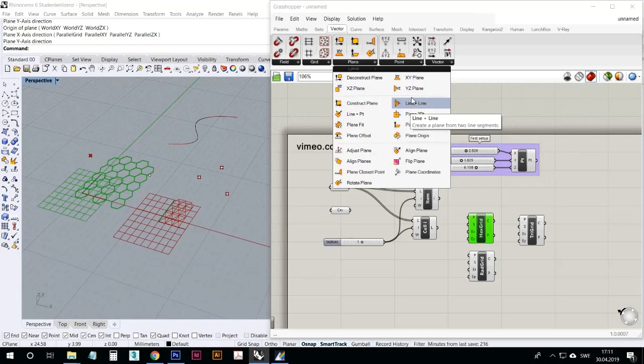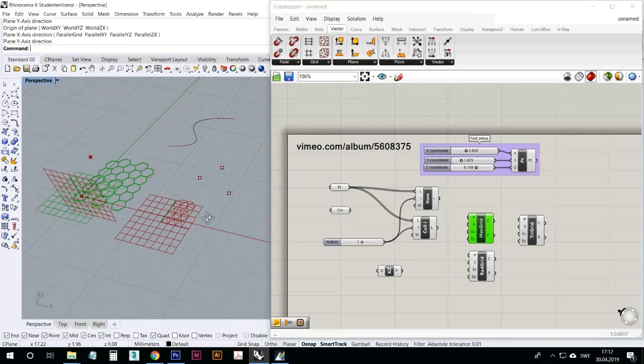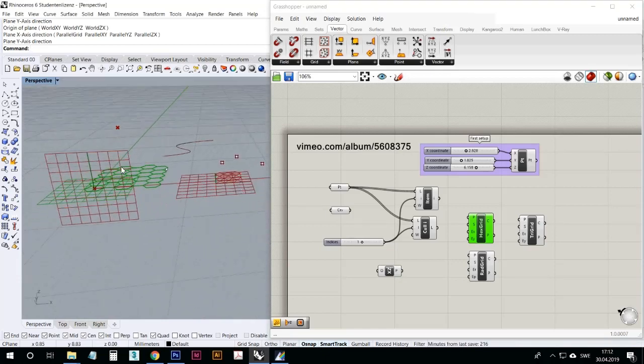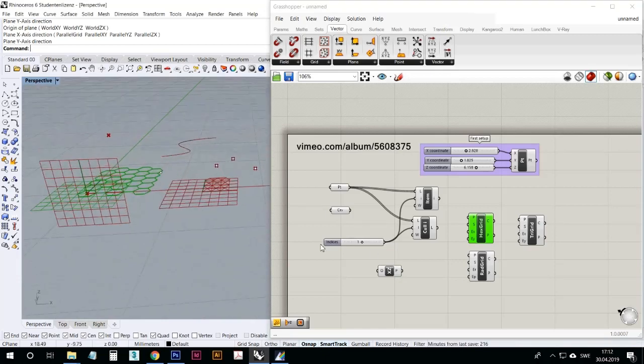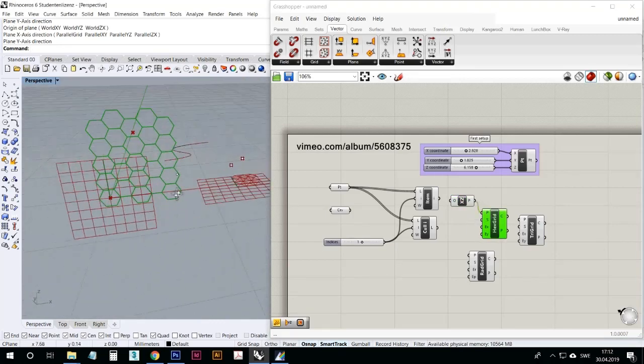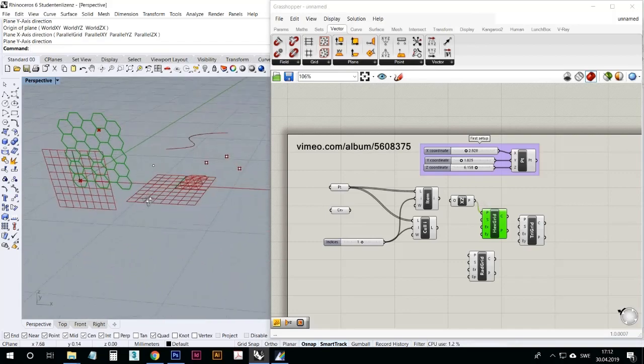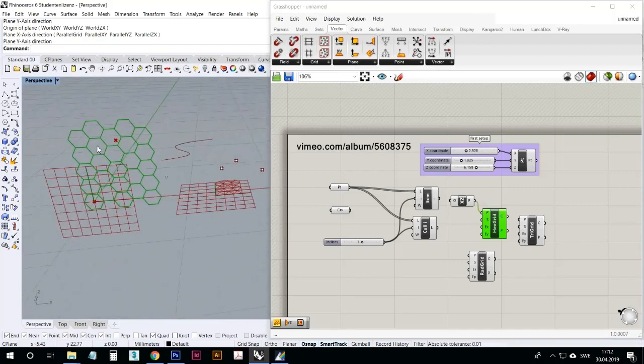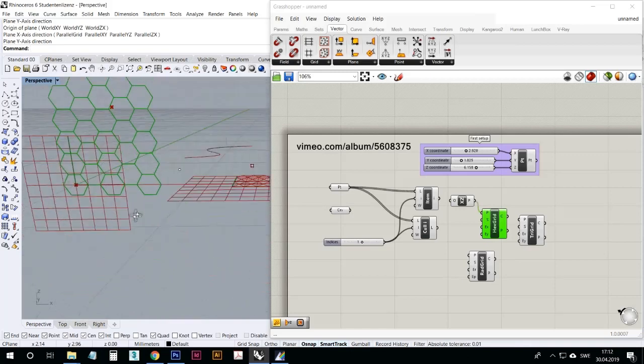You can also draw directly in front view, for example, or in right view. So if you use this, and I'll take that out, anything you draw on this will be drawn in front view. This is an XZ plane, so if I add that instead, the whole pattern, the hexagon grid that I made, the tessellation here, is going to be situated accordingly.